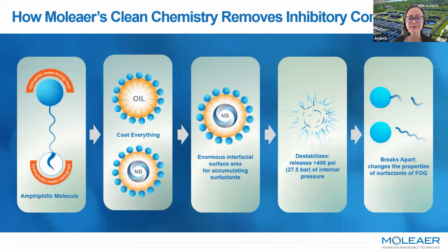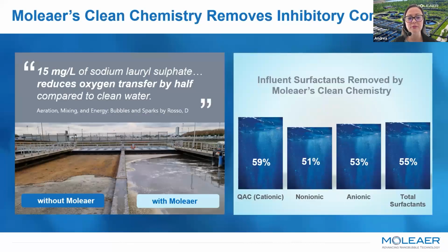Breaking apart these surfactants and changing the properties of the fat salts, grease, and surfactants. This helps to explain what we see on the primary clarifier in the photo below. The complete removal of that scum layer within less than 1 week of operation is due to the breakdown of those surfactant compounds that were creating that gel-like stable emulsion at the surface of the water.